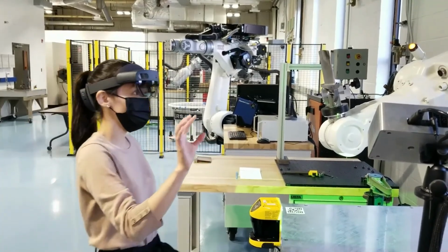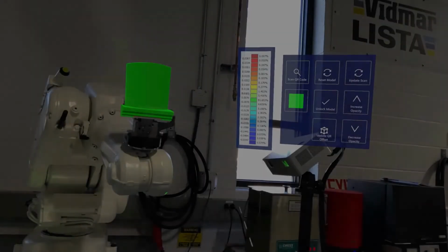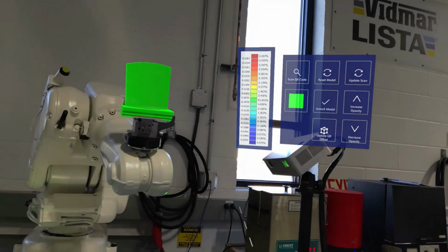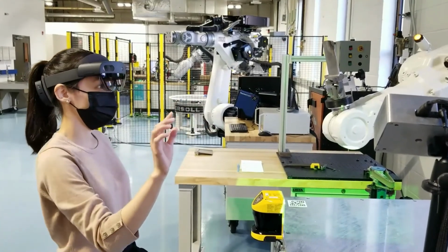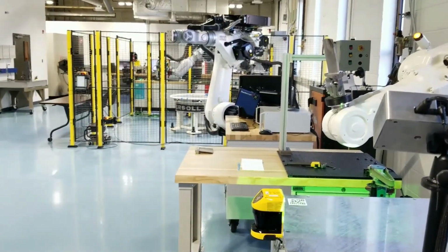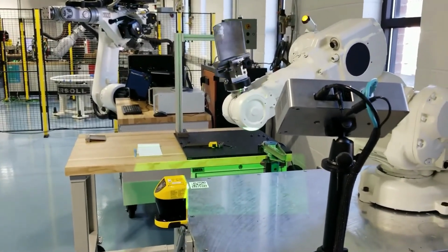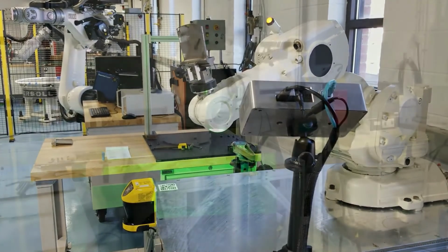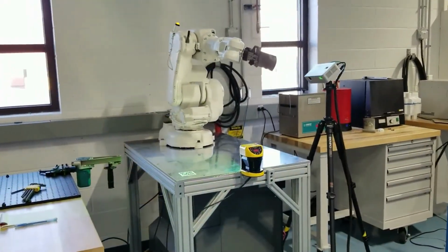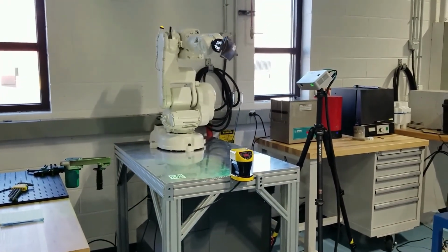One thing to note, though, is that robots are typically a little bit less accurate than a CNC machine, so you typically would use compliance or some other means to take up any little deviation that the robot may have in its path. For a sanding or grinding application, it works quite well where you're blending and removing tiny amounts of material at a time. So the sander actually has a little bit of give in it to take up the irregularities of the surface. It really helps smooth things out, keep it nice.